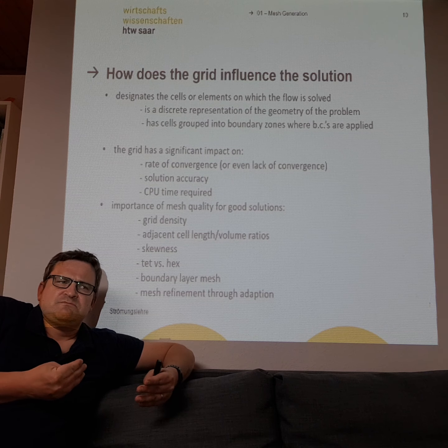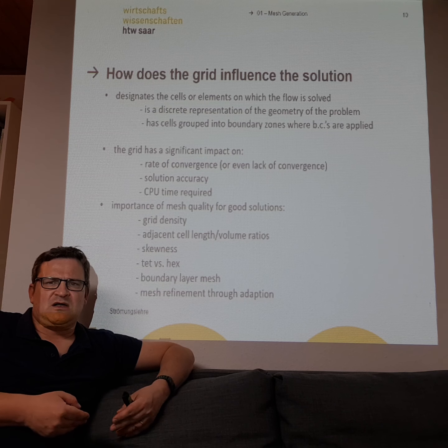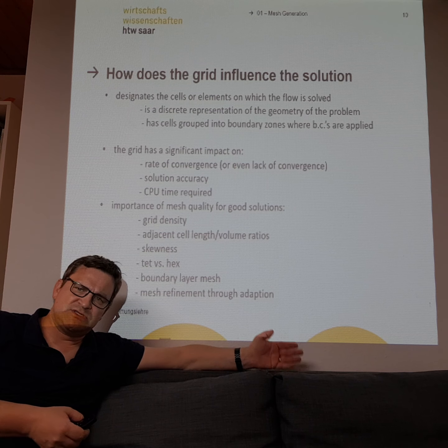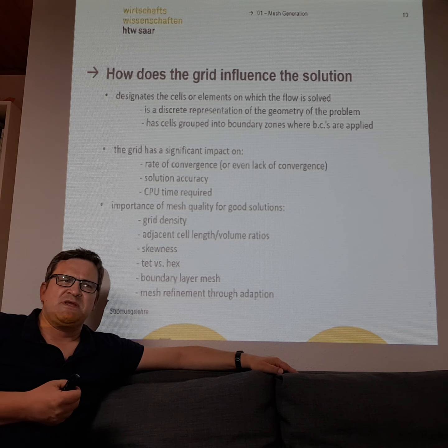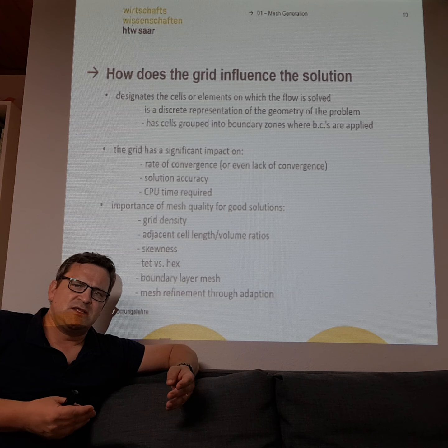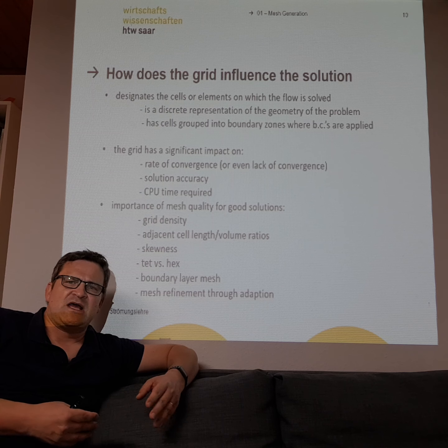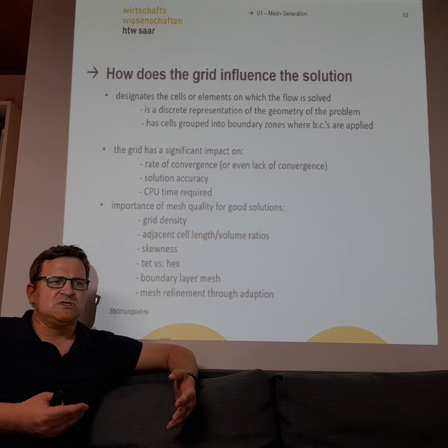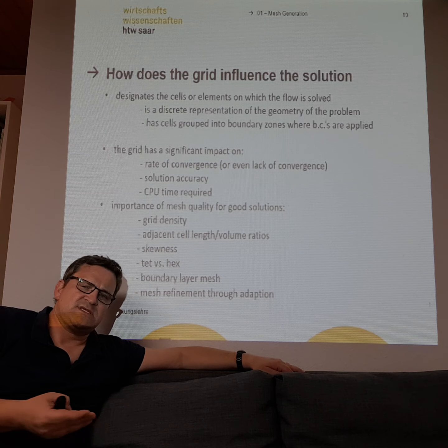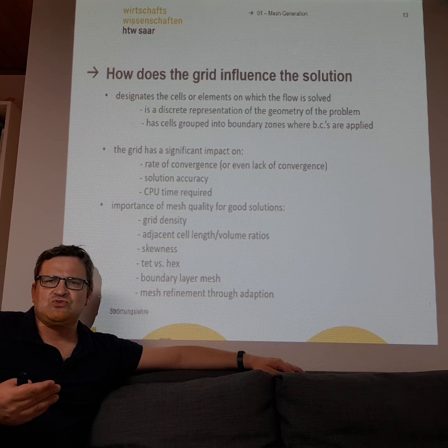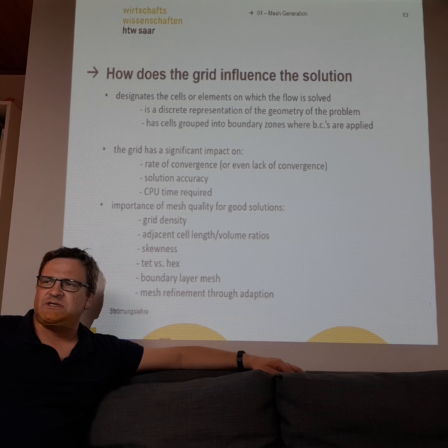But there are other things. Maybe you don't have so much money, maybe you don't have such a good computer. CPU times are important. Can you solve the mesh? Can you solve the solution? Beginners always make the same mistake. They build big meshes with millions of cells. They spend many days building a big mesh, and afterwards they realize, oh, my computer is too cheap. I can never solve this problem. Then they have to step back. They have to make a coarser mesh, and they lose quality.